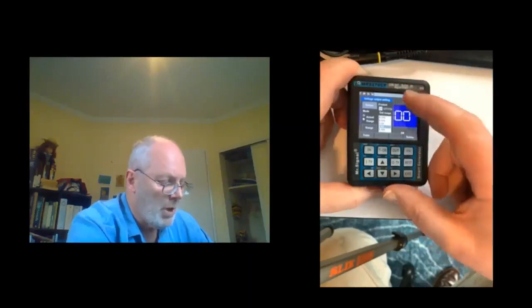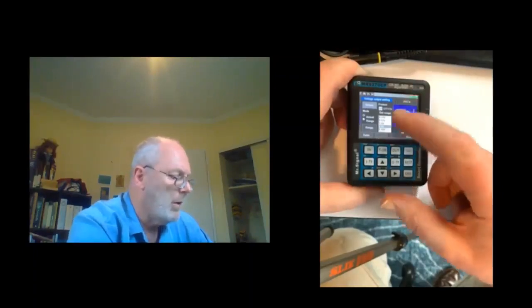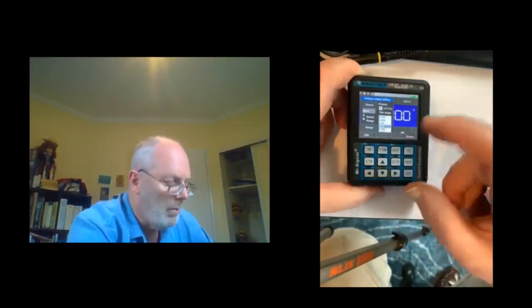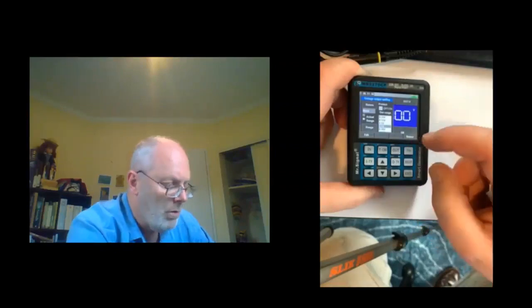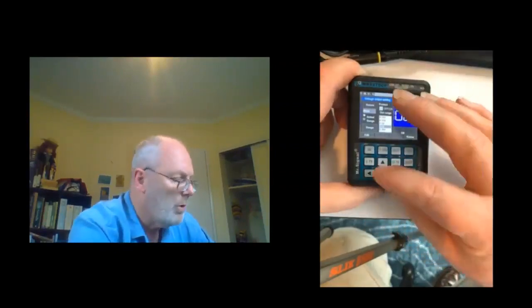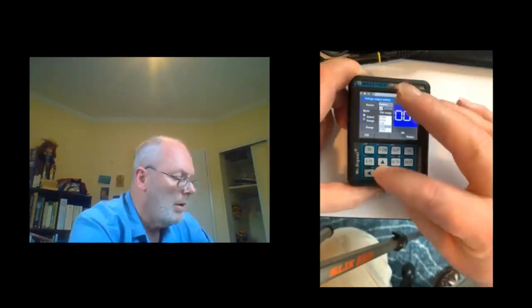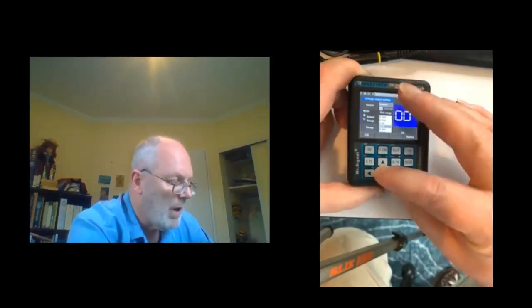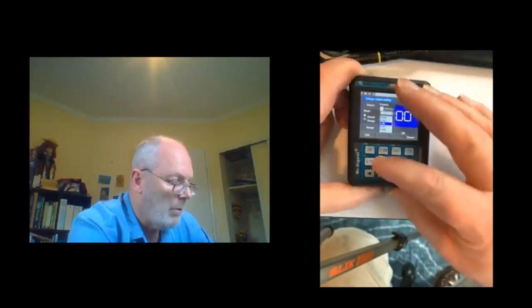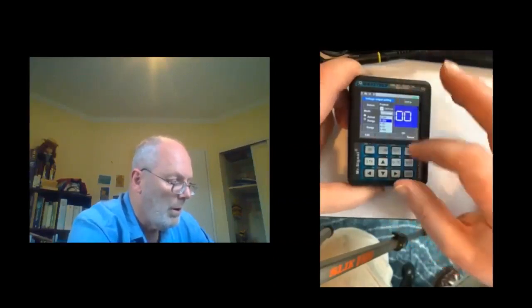So in this case we've selected voltage, so we can use the arrow key to go into the mode and select either a range. So if I edit that, I can select a range or an actual voltage. I'll select edit. I'll select actual. We can turn on voltage protection, and we can select the voltage range. So we go to edit. Let's say we want to go from 0 to 12 volts. Return.